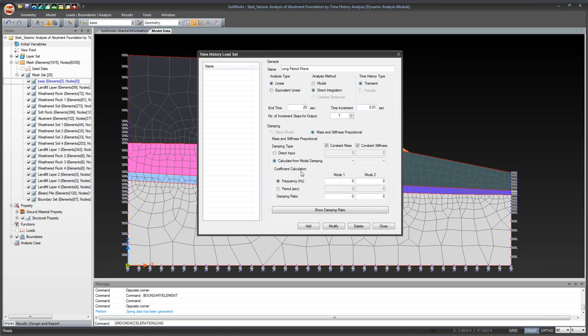And then modal damping. Here we'll input manually. For the frequency, let's make it 1.7897, and I'm getting these values from the tutorial that was provided. I gave you all a copy of this, so you can look into it further afterwards. These are just the default values assigned by the tutorial. Depending on the wave you're using, these modes will differ. The second default value given is 3424. And then the damping ratio, which is the same for both modes, is 0.05.